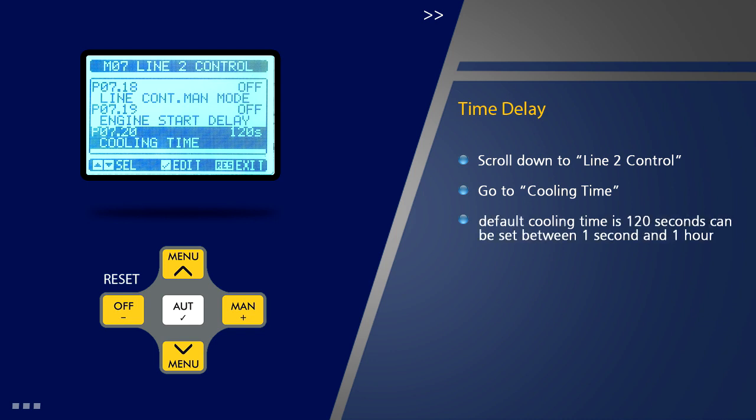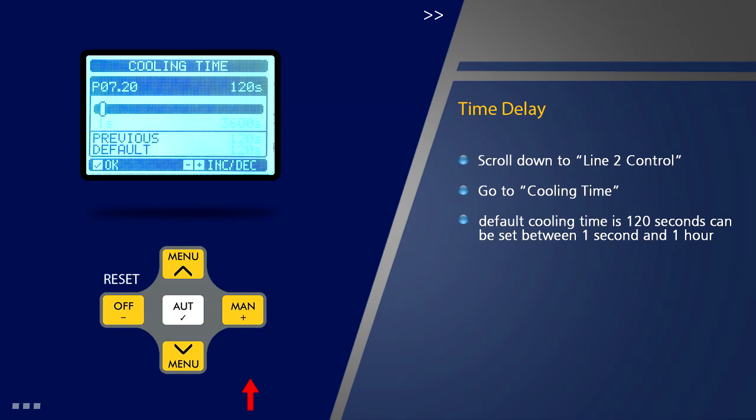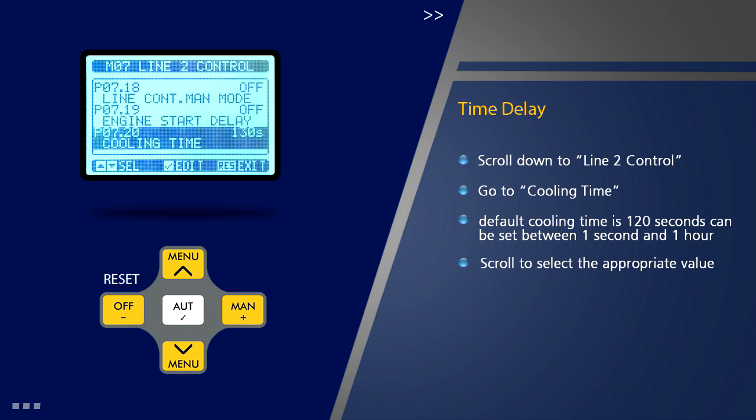The default cooling time is 120 seconds and can be set between 1 second and 1 hour. Scroll to select the appropriate value and press OK. Press Off to return to previous menu.